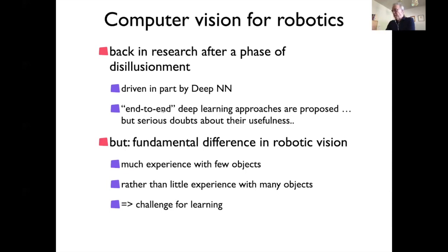While a lot of the computer vision algorithms are based on having limited experience in just single images or small clips with many, many different objects. And these many objects would essentially explore all the variants, and then you extract the invariant component that helps you classify and maybe estimate. That means that the assumptions of these algorithms are not necessarily valid in the case of robot vision. So that's one of the challenges of that.